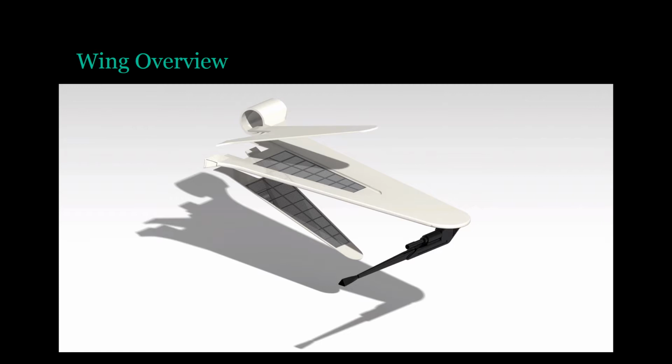The main wing also has a hole in its central area where a radiator is placed to aid with heat dissipation. Additional auxiliary radiators are also located on the inner surfaces of the wing's S-foil winglets. When the S-foils are folded out as pictured, these radiators are exposed to external conditions, which will aid the aircraft in dissipating heat generated by its cannons while in combat. These S-foils were also modeled by tracing their main profile using sketch tracer and using GSD to help with creating the curved joint by which these S-foils attach to the engine casings.